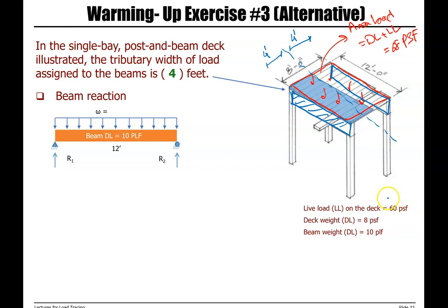The area load, dead load and live load, is 68 psf, and tributary width of beam is 4 feet.